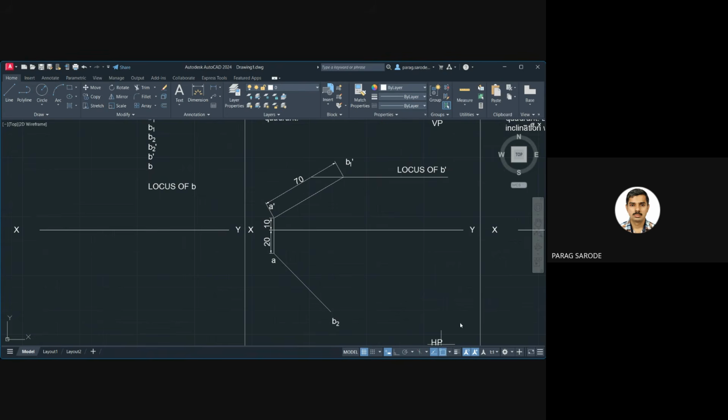At the same time, I will show you this with OSNAP tracking off. Now it is off. I can select the endpoint, but I cannot draw this line because I can't see the projection. One thing to take care of here is ortho mode on and off. We need to do it simultaneously sometimes. So now I will switch it on again.